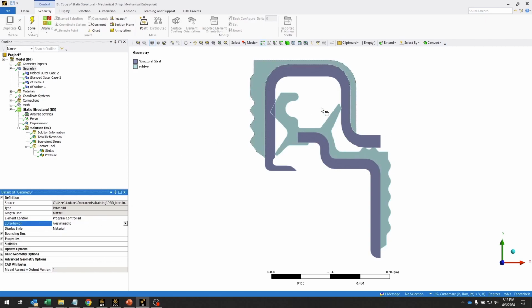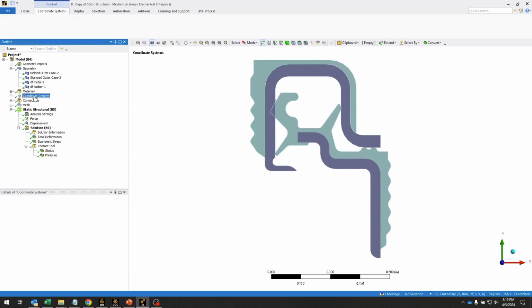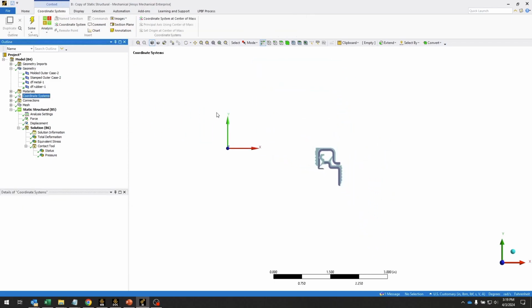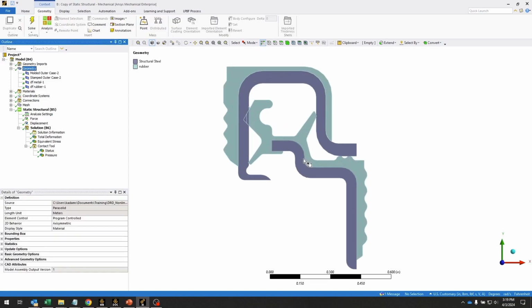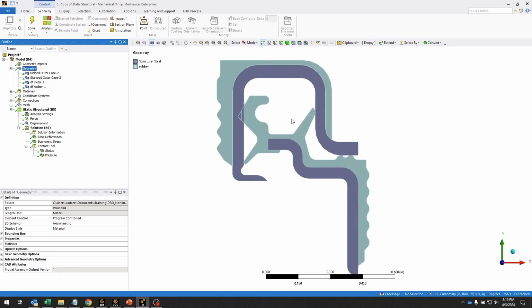It is a 2D axisymmetric problem, so you can imagine this 2D slice being revolved around the global y-axis to create the full 3D geometry that we're modeling here. You can see that this assembly is a mixture of rubber and steel parts. And the physics of the problem are that we want to resolve this initial interference, and then we also have an annular spring body here that's exerting a force in the inward radial direction.